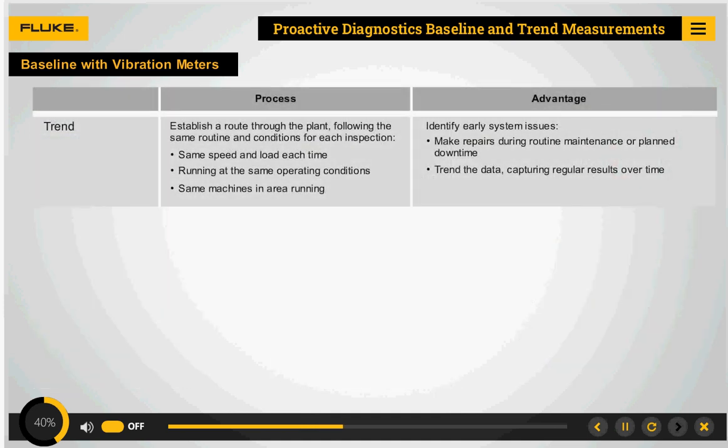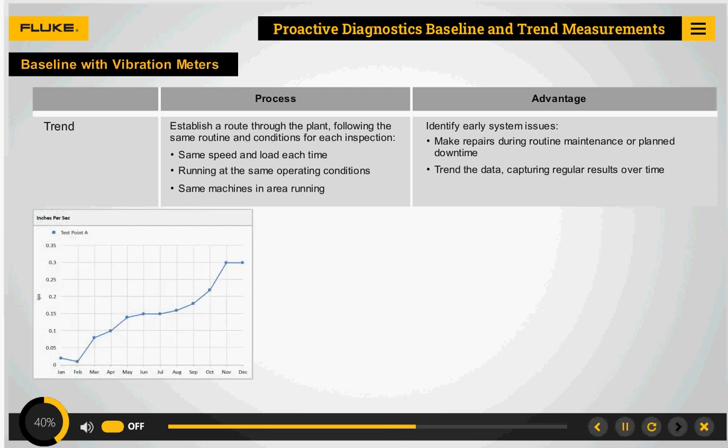After measurements are taken during the rounds, results can be easily uploaded into Excel. From there, you can trend with pre-configured Excel templates and plot graphs and compare the overall vibration readings to ISO standards 10816-1 and 7. If there is an abnormality, it can be identified by using the trend charts. This enables you to see a clear picture of the changing bearing condition and deteriorating health of the machine.